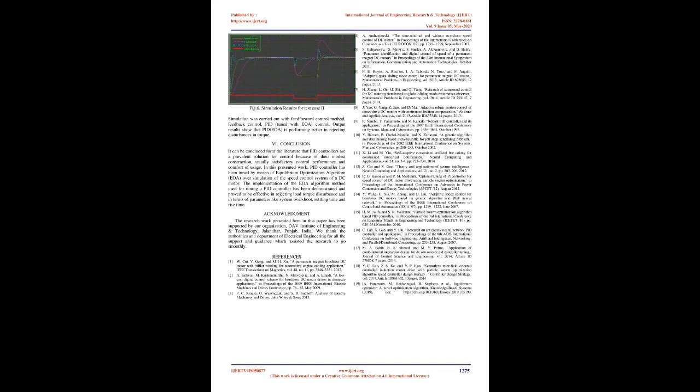V. Results and discussions. EOA is used to find Kp, Ki and Kd gains for PID control of a DC motor. The population used for EOA was 20 and the maximum number of iterations performed was 40. Test case I, neglecting disturbance torque. For this case, DC motor parameters used are given in Table 1. A unit step signal was given as input to the simulation model given in Figure 2. First the simulation was run with IAE as fitness function and then with ITAE as fitness function.